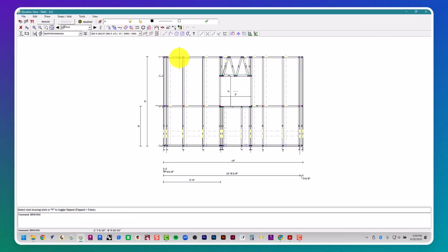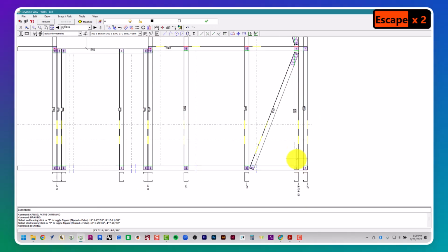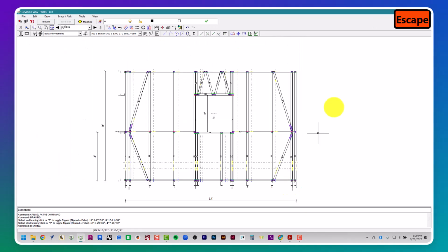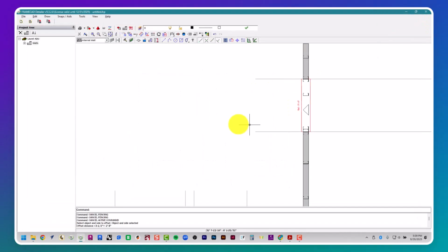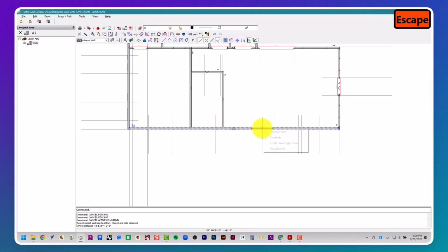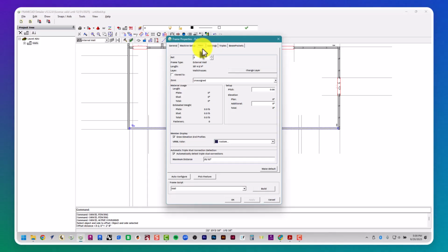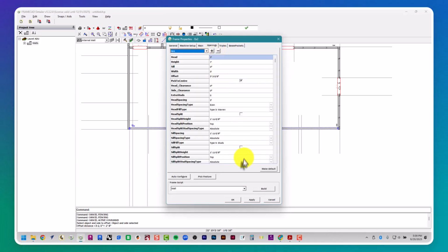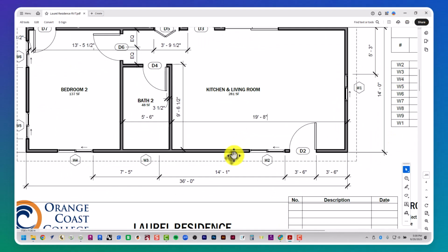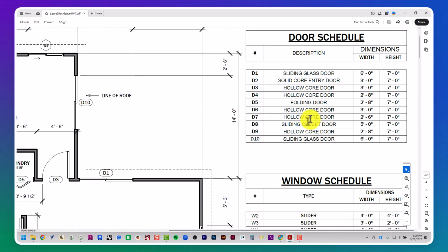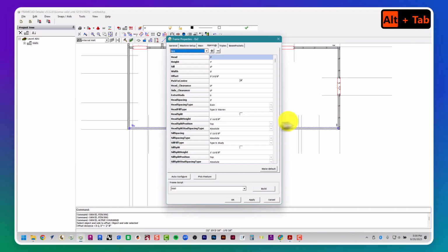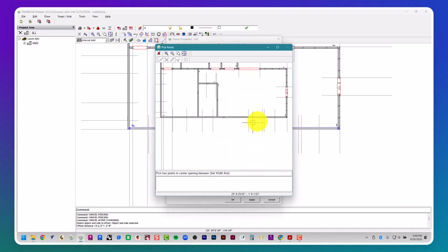And we can go ahead and automatically add some bracing, making sure that that bracing gets accepted into another stud, like an open face stud like this one. Okay, so that just adds some additional bracing to that wall. Let's go with this wall here. Main, 9 feet, openings, plus. And the first one we'll do, let's start with D2, which is 3 foot 7. So 3 foot 7.